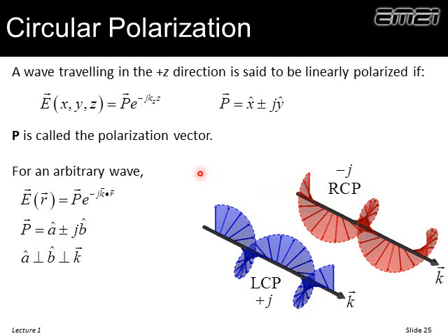Optics folks look at it the other way around. The eyeball's over here on the left, and they're looking at the wave traveling away, and we look at the way the electric field rotates around that axis. So optics folks and electrical engineers have the opposite definitions of polarization. What an IEEE journal would call right-hand circular, an optics journal will call left-hand circular. So keep that in mind.